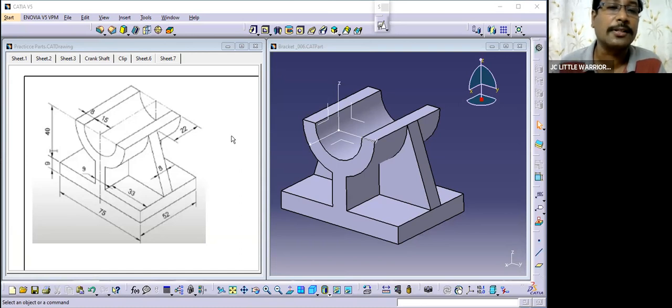As we discussed initially, if we want to follow exactly the manufacturing method, what do we have to do? First, we take a block of metal of this height and this width, and then we start removing material and achieve this profile, this pocket.